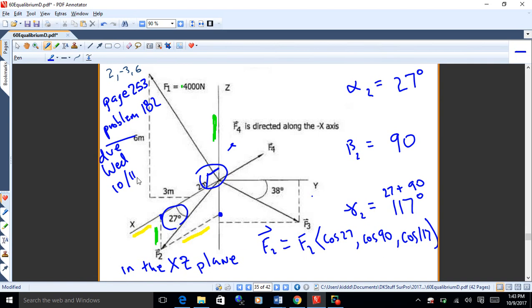All right. Now we got a couple minutes, so I want to start something new, but that's the 3D equilibrium. So for 2D equilibrium, the way I do it, I just kind of look at it and figure out the trigonometry. The 3D, I get more systematic. Make Cartesian vectors out of all the vectors, put them in columns in a matrix, and solve out the rows. That's how that goes.